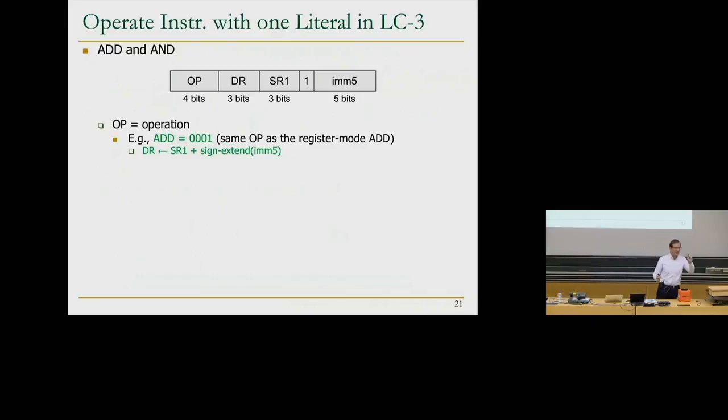So you have 5 bits over here. The top bit is a 1. That means it's negative. If you want to sign extend that value to 16 bits, the remaining 11 bits at the top will be all 1s. If you want to sign extend a value that is positive or 0, which means that it has to start with a 0 at the most significant bit, you basically fill the top 11 values with all zeros. Makes sense, hopefully. You basically sign extended a 2's complement value. And that's the idea over here, so that you can add it to a 16-bit value that's in the register.